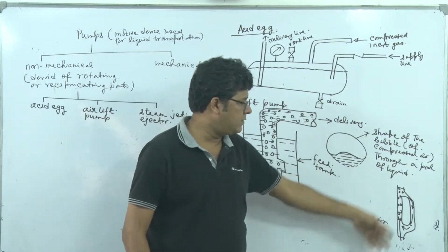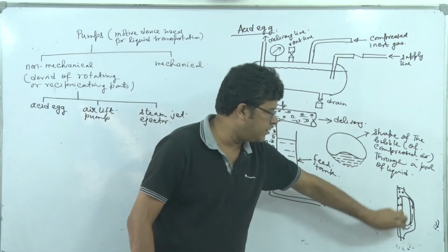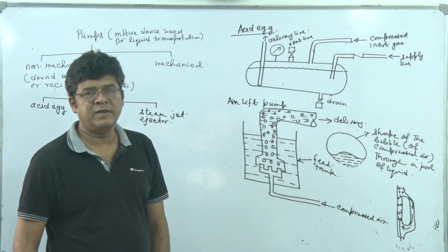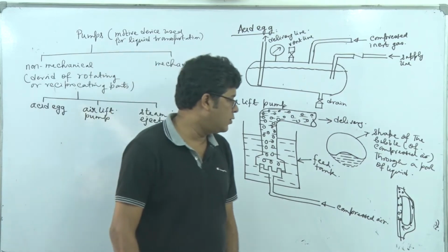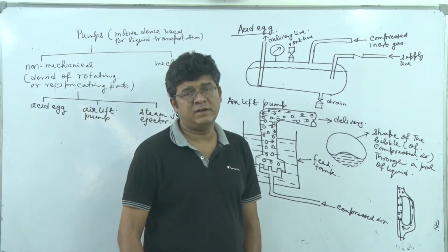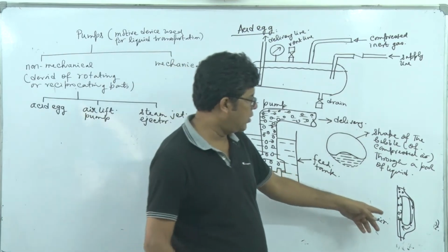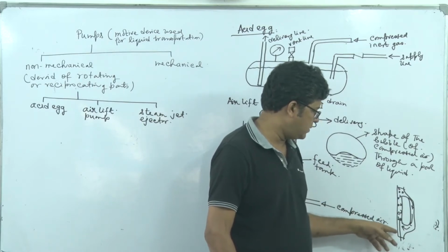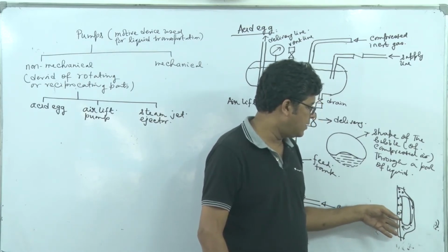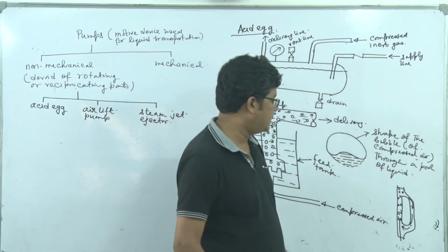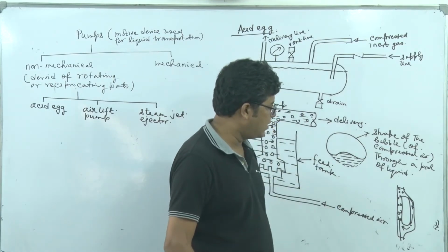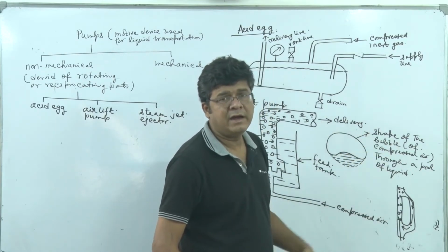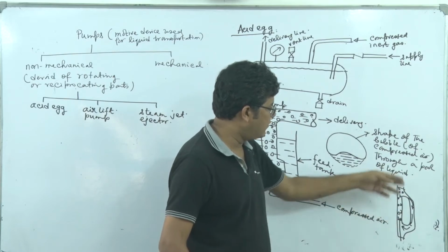Because whenever this microorganism, say if I am feeding a pump here, passes through these impellers or the piston, it will be strained and the shell may tear apart. So in order to have a non-sheared system, a non-mechanical system where we don't have any moving accessory like a rotating or reciprocating part, the cell will be intact and maintain its regular functioning.